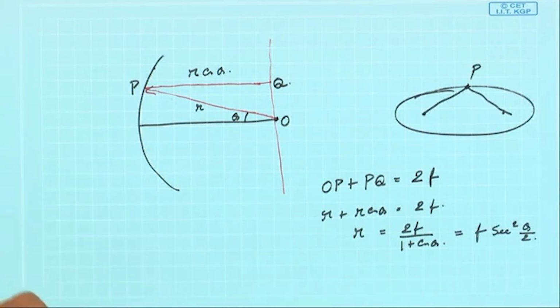The power is viewed as flowing in a flux tube, and if a flux tube is reflected from a perfectly conducting surface, the power in the reflected flux tube equals that in the incident flux tube. These are all results you know, I am just saying it, that the electric and magnetic fields are transported along the flux tubes. The electric and magnetic fields are mutually perpendicular and orthogonal to the rays, because rays are the direction of propagation.